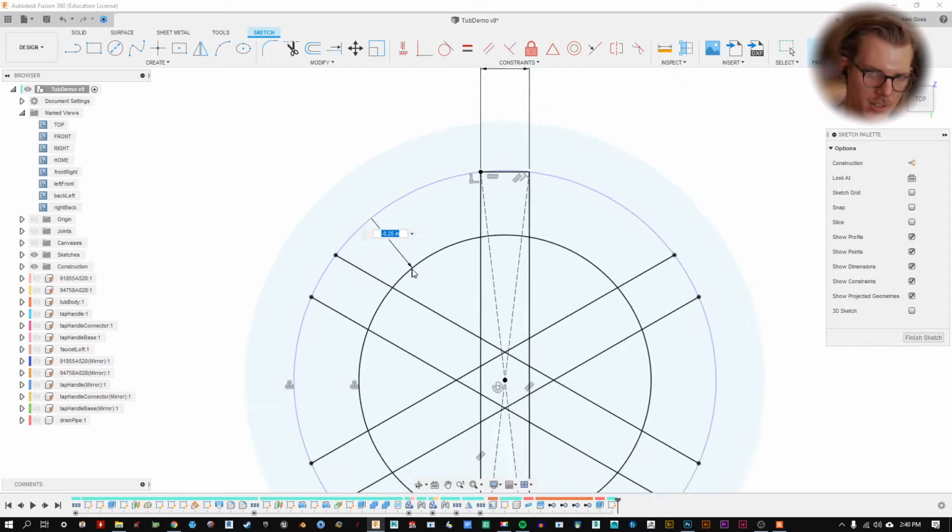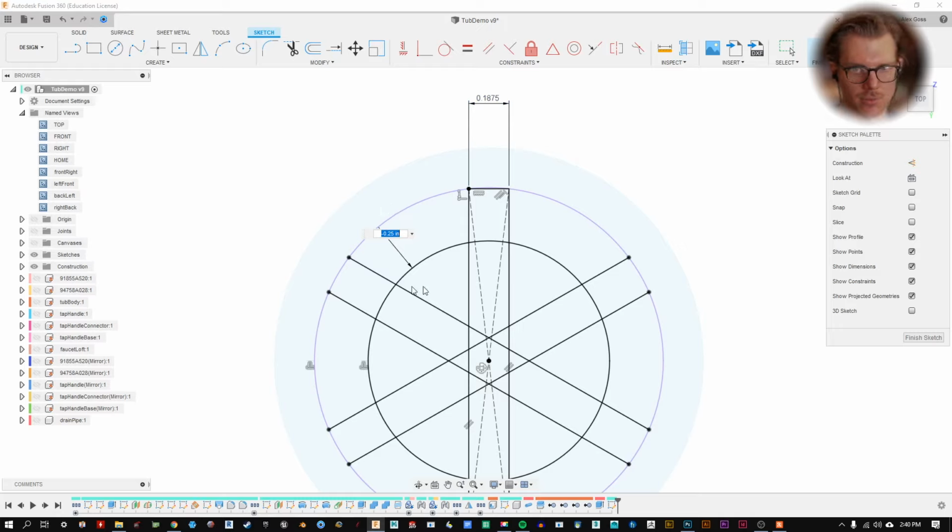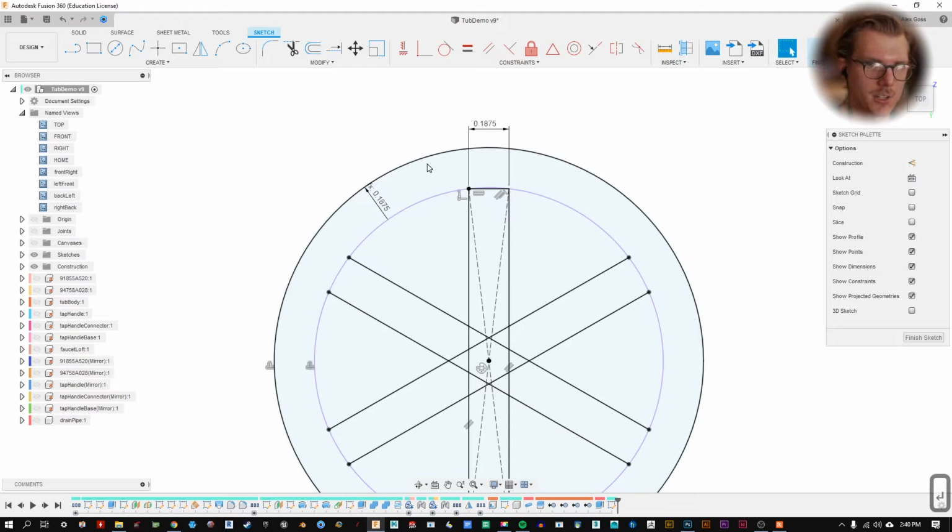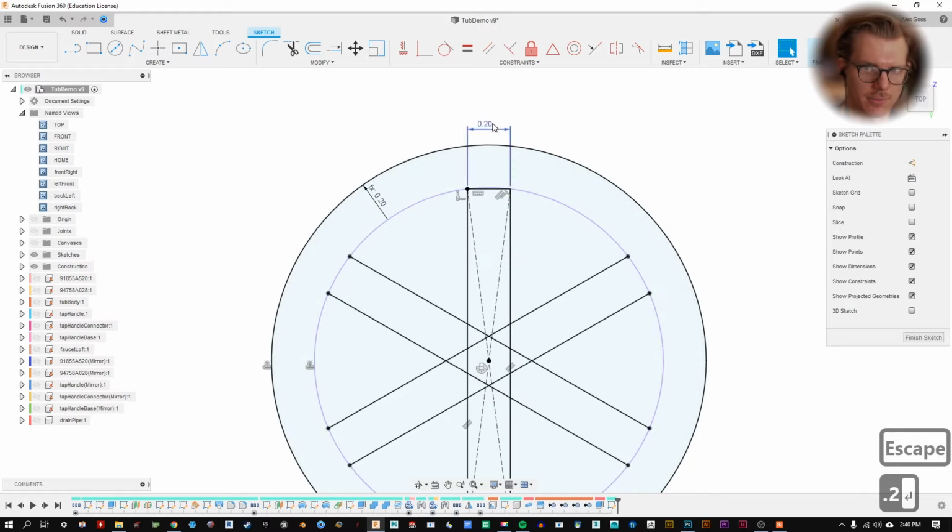So if I want this piece to reference that piece, it's probably better to start with this being the driving dimension as just a positive, like think of it as an absolute value. And then here, if we make that equal that, I can just click on another dimension. See, this is D, dimension 104. If I hit enter, it will say X. Now we have a formula, X equals D104. So if I change this, it'll change that.